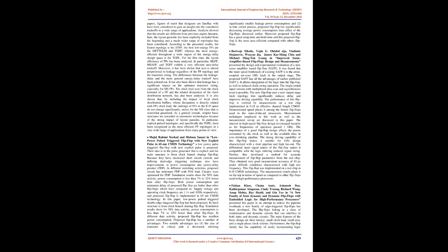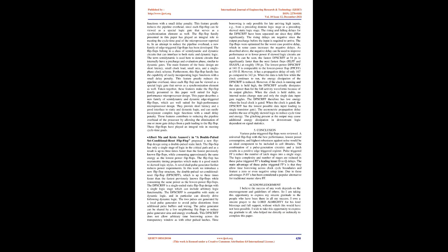Borivoje Nikolic, Vojin Oklobdzija, Vladimir Stojanovic, Wenyan Jia, James Kar-Shing Chu and Michael Ming-Tak Leung, in Improved Sense-Amplifier-Based Flip-Flop: Design and Measurements, presented the design and experimental evaluation of a new sense amplifier-based flip-flop, SAFF. It was found that the main speed bottleneck of existing SAFFs is the cross-coupled set-reset, SR, latch in the output stage. The proposed SAFF has all the advantages of earlier published SAFFs.